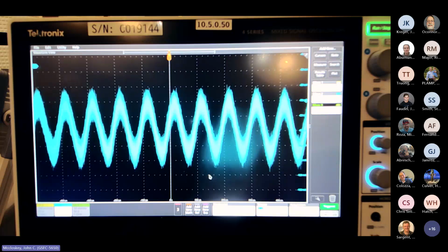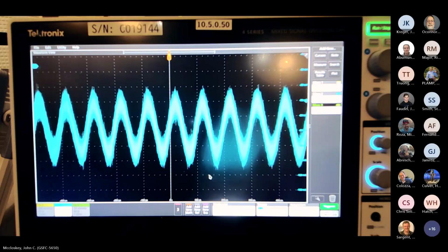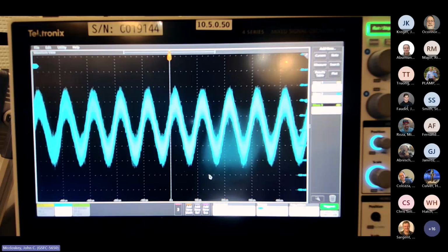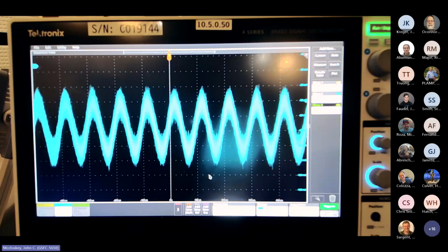So this is our short circuit current at 10 kilohertz. Our pre-calibrated level was 3 milliamps. Normally, when you're doing this as part of a control loop, you would level at 6 dB higher than that pre-calibrated level in the plateau, so 6 milliamps.